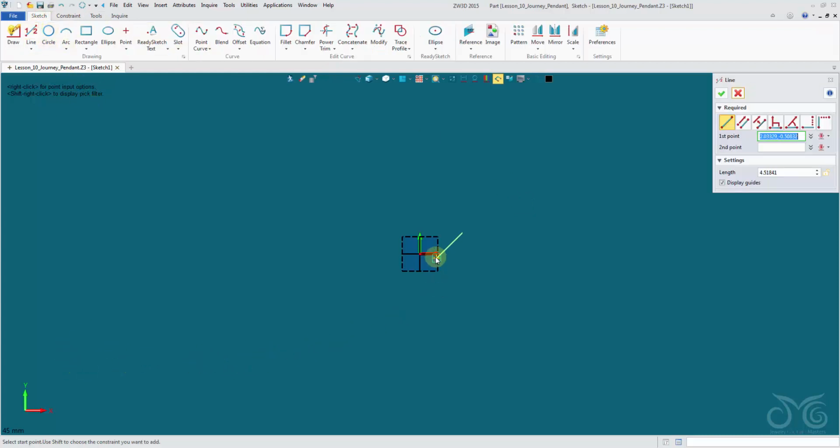Okay, and I'm going to create a skeleton. Okay, so I'm placing some lines, 2-point lines. I'm going to let this one constrain vertically. Another one. Down to the bottom. Let's let this next line snap to the midpoint of our first line. Okay, so you can see the midpoint constraint icon there. Left click, keep it horizontal. Okay, we'll bring them out like this. Again, we'll snap this one to the midpoint.